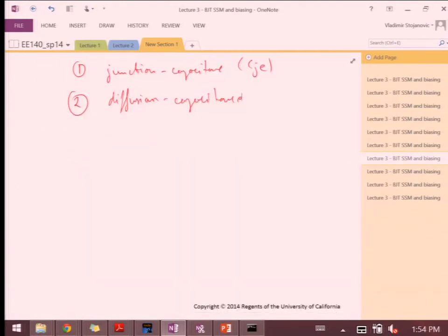And to really understand what it represents, we're going to say that anytime we inject an electron into the base, it sort of rushes through the base with some speed, right? So it spends some time in the base. And I can sort of calculate what that speed is by saying, oh, hey, I have a total charge, total number of electrons.